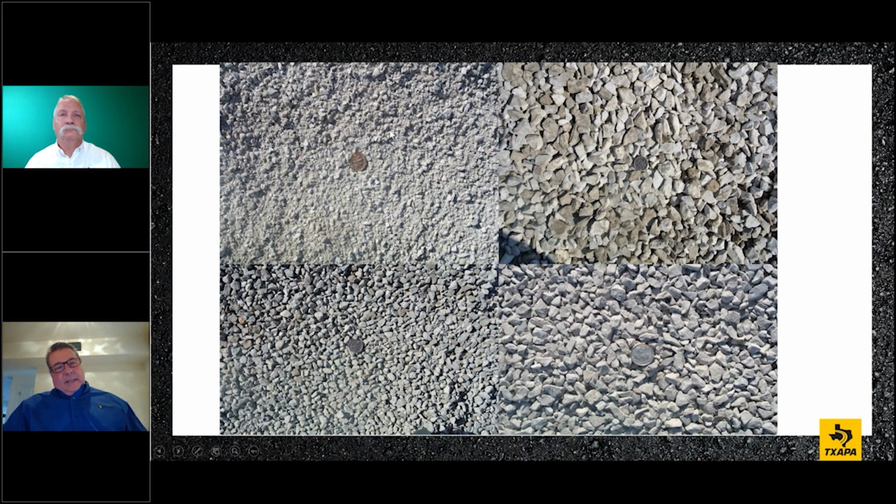There's nothing that indicates this is going to give us any kind of issue. But it's real important to pay attention to your stockpiles. If your stockpile, after your loader bucket comes out, is standing straight up and down, you have some clay in there. You want to check that. You want to make sure you don't have the bad clay, the methylene blue bad stuff, in there. But anyway, again, very uniform.